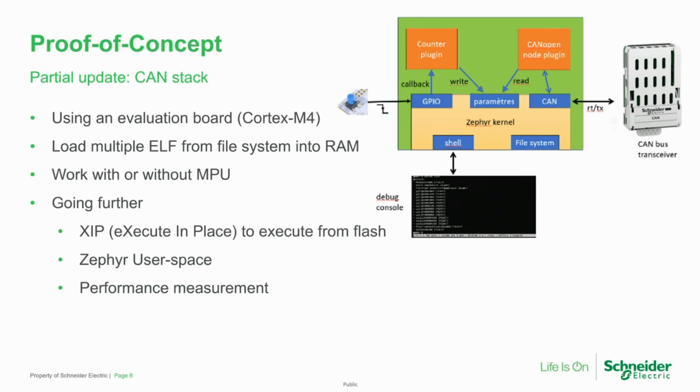we started two extensions. One was very simple, which was a counter. The extension was only incrementing a variable inside the base firmware, and we had the other extension, the CAN stack, on the LLEXT, and then we were able to communicate with it on the CAN bus with the host. We have the CAN bus between both. The host was triggering a CAN connection and exchanging some frames on the CAN bus.